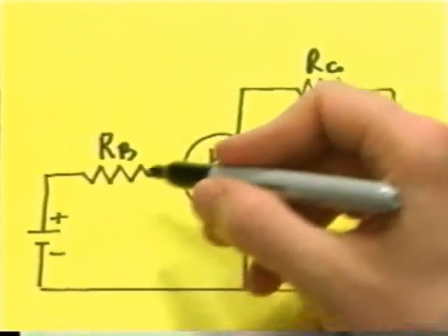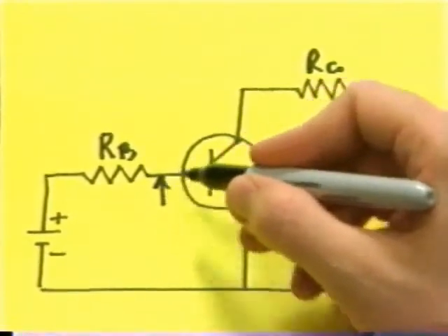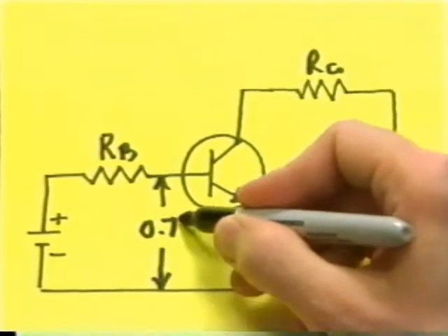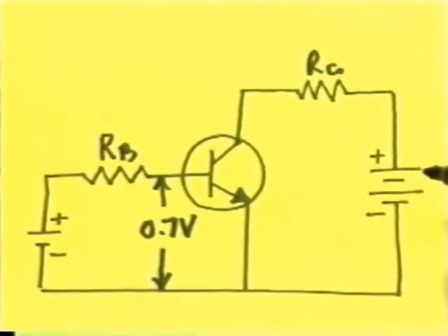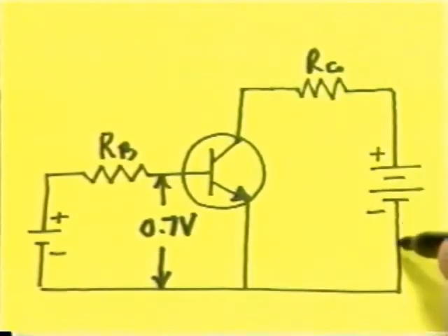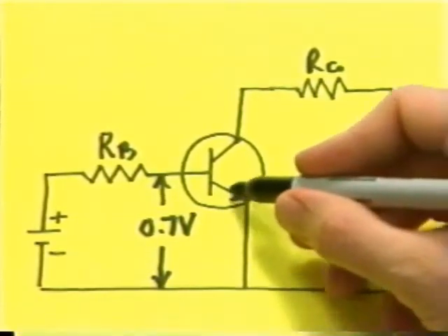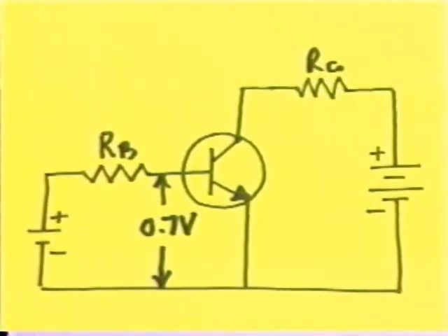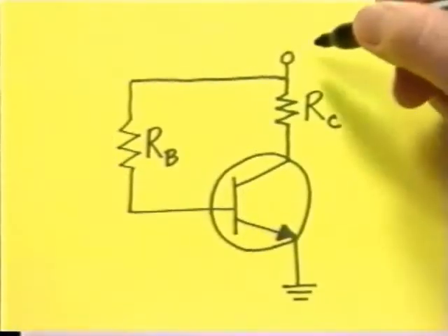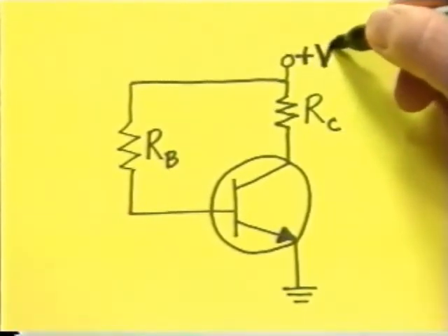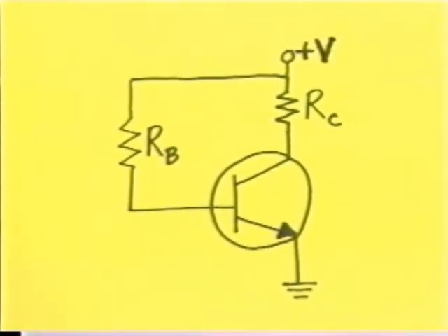The magnitude of the voltage source on the emitter only has to be high enough to overcome the barrier potential and forward bias the emitter-base junction, 7/10 of a volt for silicon. The collector voltage, on the other hand, is usually much higher because it must provide enough attractive force to draw the electrons through a reverse bias junction and into the collector. In reality, a single voltage source can be used to satisfy both criteria, which you can see connected to this basic transistor circuit.